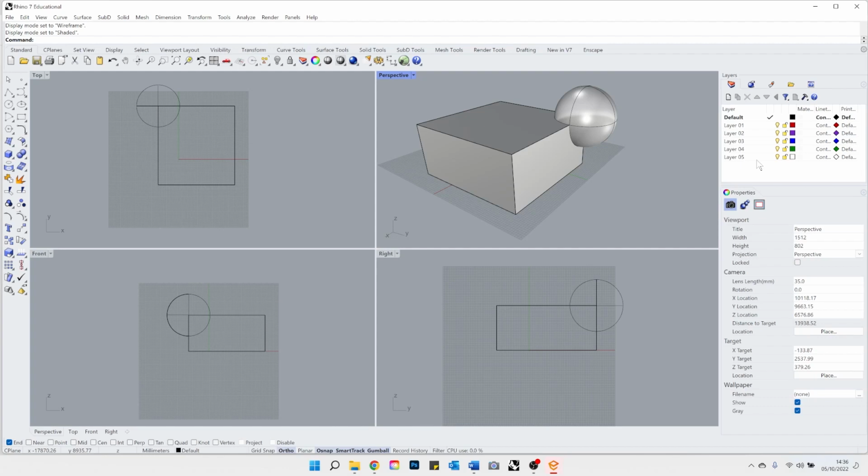So if you have models that you work in, for example, you know that your final outcome of a model will need to be rendered, and you, for example, are making a skyscraper, and you have 50 floors, and every one of those floors has 50 windows. So 50 elements are going to be representing glazing. You will not want to go 10 hours before deadline, selecting every single glazing, moving it into a separate layer, applying a different material to it.